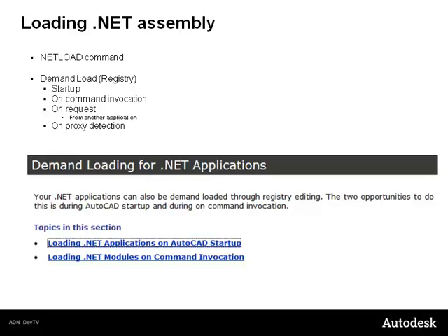This command can either be invoked manually by simply typing the custom command name on the AutoCAD command line, or fully automatically on Civil 3D startup by implementing an auto startup macro.